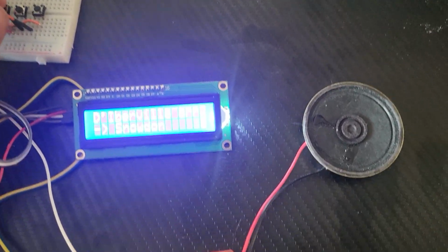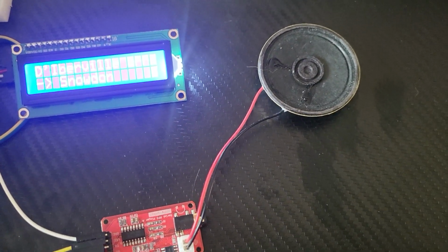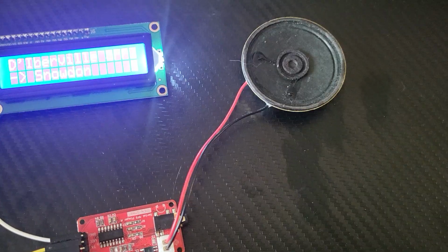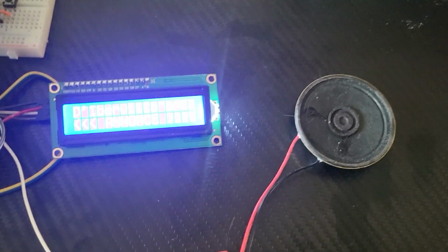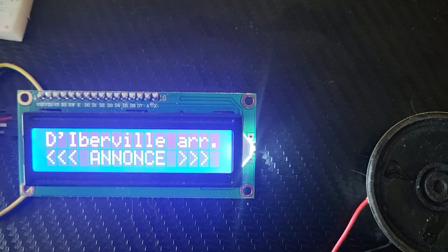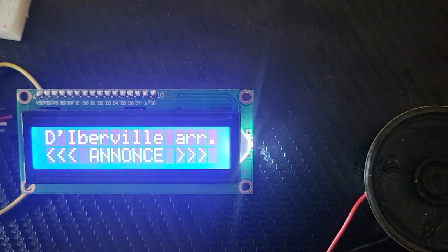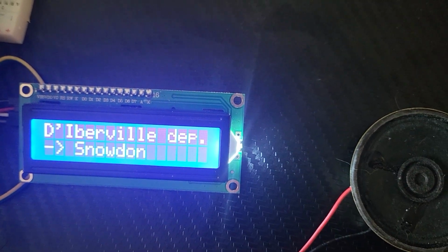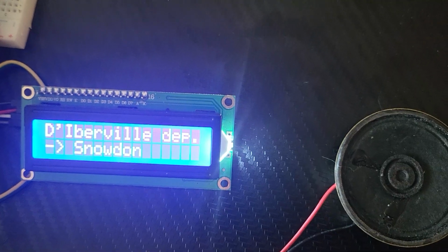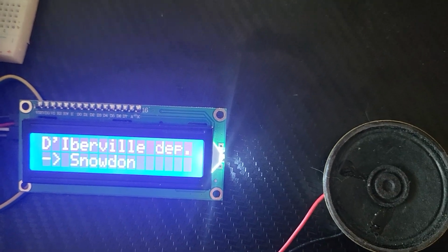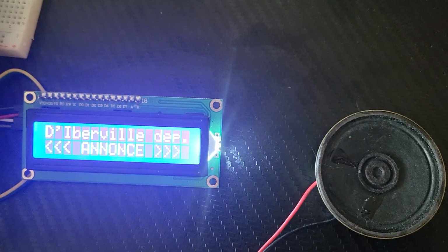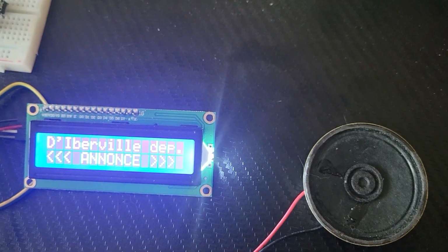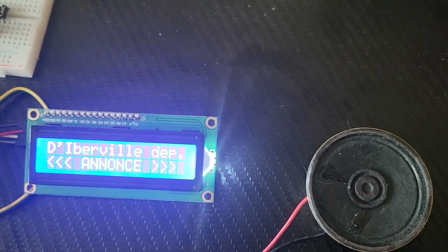And the LCD refreshes on a timer when an announcement is actually playing, and the green light that is on the MP3 player shows when audio is actually playing, because sure, it does say announcement over here in French, it says annonce, but after some time it just stops. Sometimes it stops after the announcement is playing, sometimes it stops before because the LCD is on a timer. There's no way to detect from the Arduino how long the audio actually is.